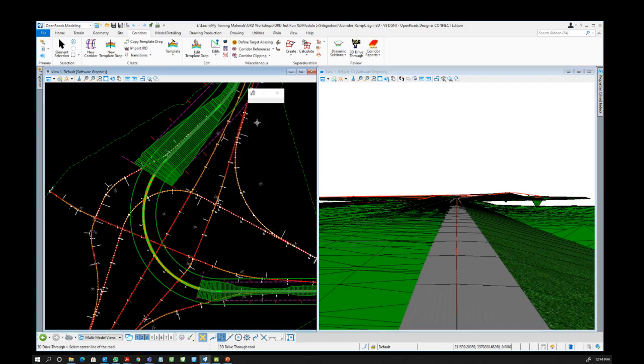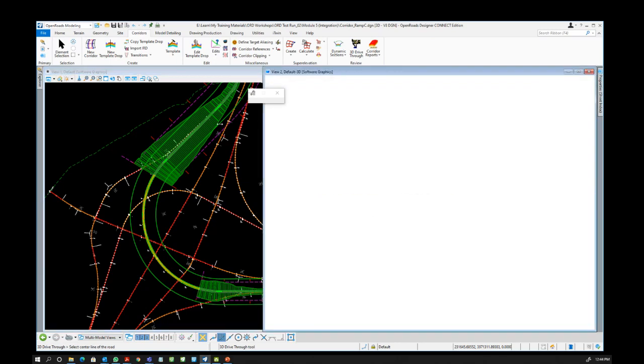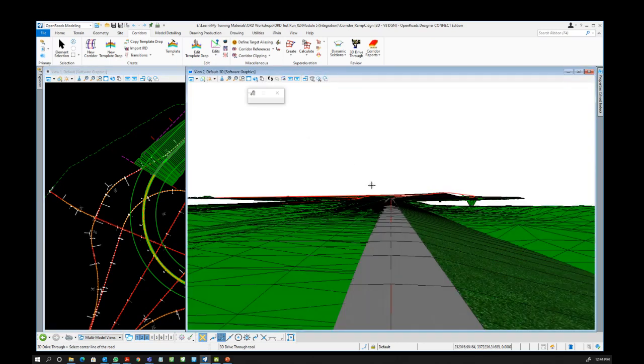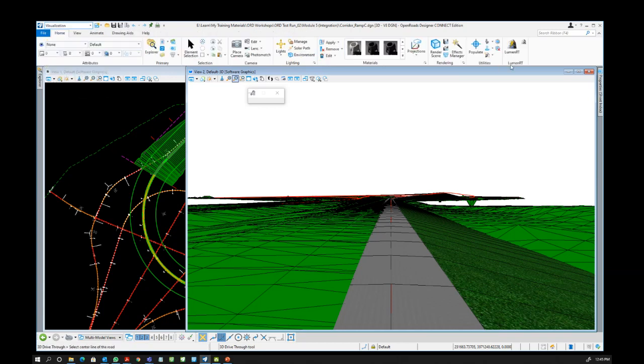Okay. Another way, if you're done with everything and pretty confident that you are finished with your design, is by using LumenRT. I will just teach you how to publish it, but I'm not going to teach you how to use LumenRT. To publish it to LumenRT, again with the 3D view or 3D model being active, go back to visualization. Then you will see this LumenRT button. By the way, before that, make sure you set your view.